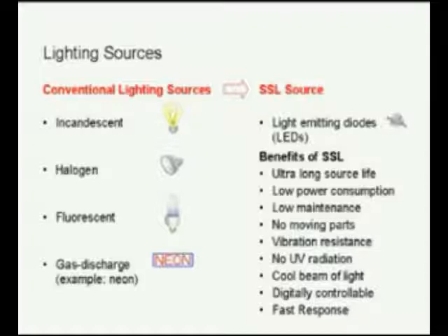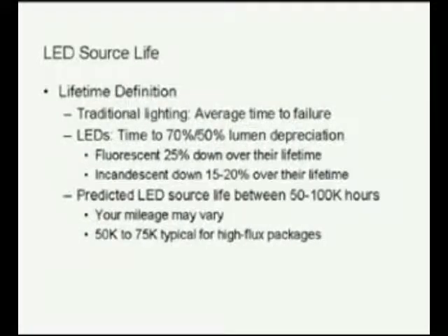have switched to LED lights rather than having the incandescent sources, which take on the order of 100 milliseconds to switch and change. That might not seem like a lot, 100 milliseconds being a tenth of a second, but if you're traveling at 60 miles an hour and respond to a light, the brake light of a car in front of you, 100 milliseconds at 60 miles an hour is about 10 to 12 feet, 3 to 4 meters, and so that's substantial at those speeds. So as you can see, there are many types of benefits and attributes to LEDs over traditional sources.